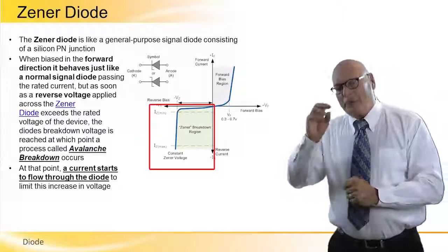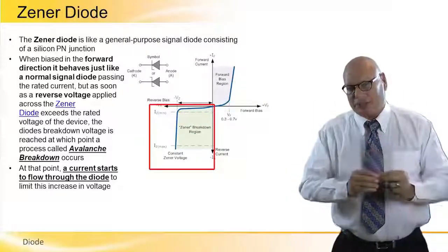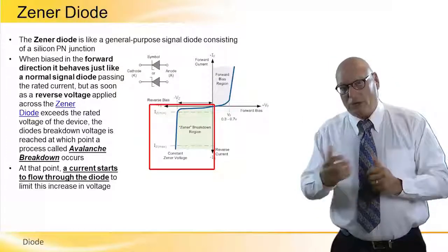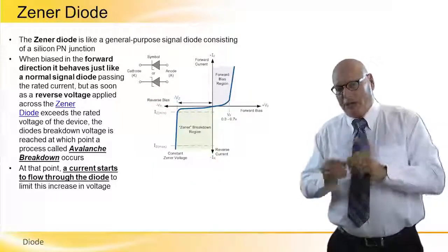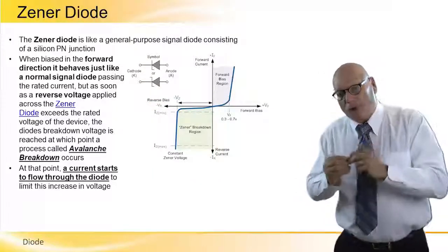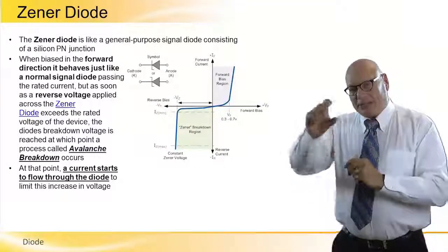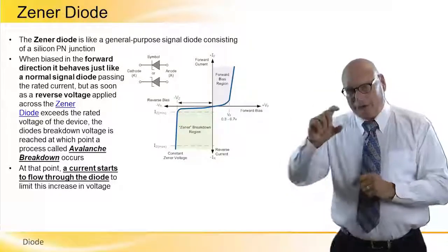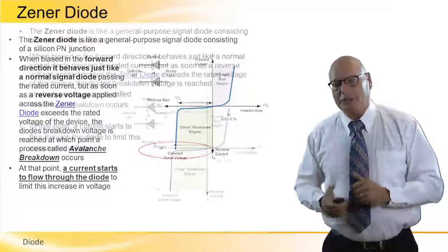Fixed based on what is written in a technical specification of the Zener diode itself. So there are Zener diodes that, in a reversed polarity, can hold 5 volts, 5.5 volts, 6 volts. Every Zener diode will have its own avalanche point. That means the voltage across, even in a reverse direction, will be fixed and can be used further on the electronic schematic. Let's look at it.